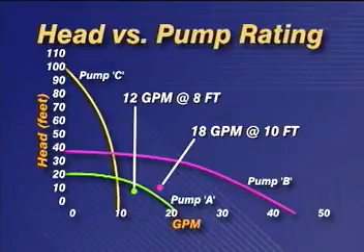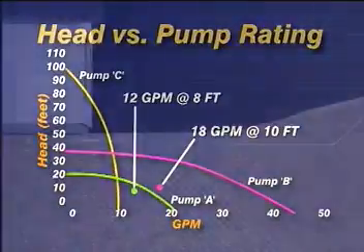One thing to keep in mind, depending on conditions, submersible wastewater pumps can vary as much as plus or minus 10% from manufacturers' published specs. So it's a good idea to build this into your sizing and selection.